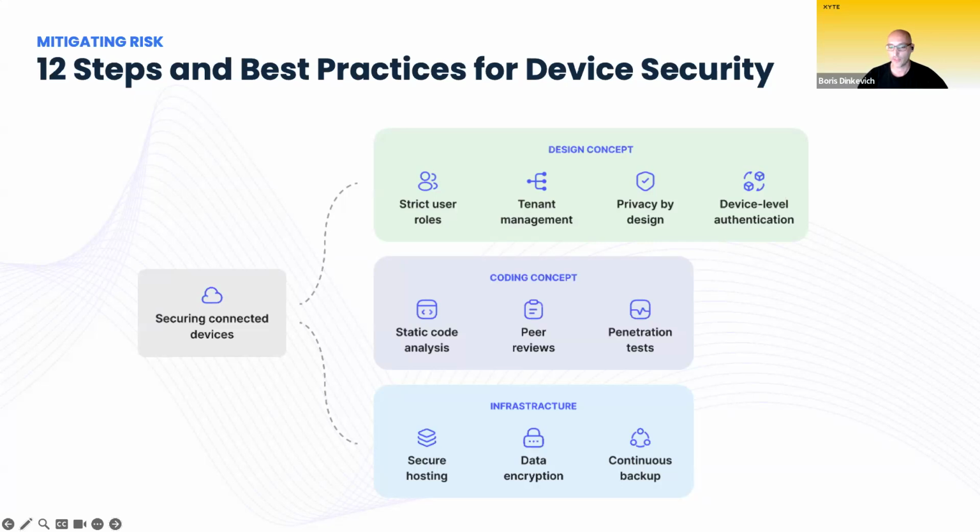So your device should never send raw data on the network. Everything should be fully secured from the device and forward. And in that place also, just a small comment, SSL certificates are very important, again, preventing man-in-the-middle attacks. I just want to stress that all the things you mentioned here as overarching concepts, there's lots of diving into each one of those, and they should be done carefully with someone who really understands what they're doing.